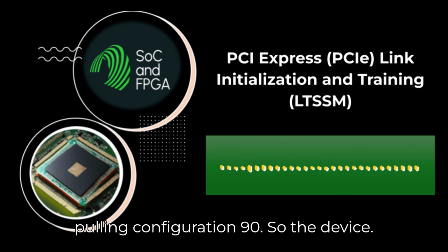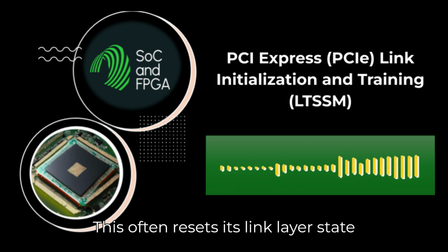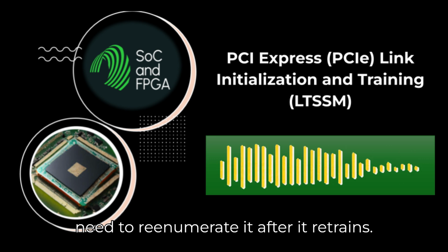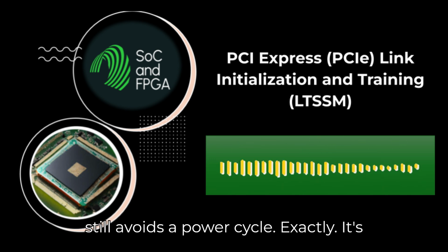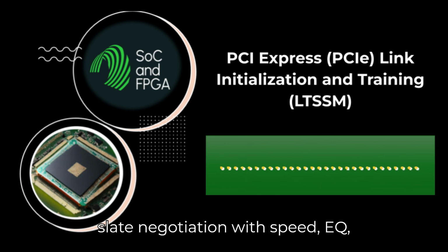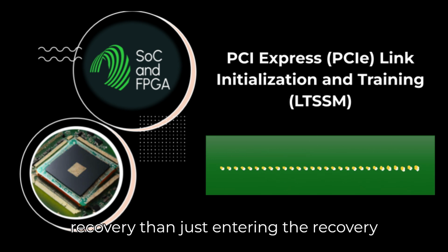Detect, then polling, configuration, and so on. For the device, this often resets its link layer state too, potentially losing its configured bus and device numbers, so software might need to re-enumerate it after it retrains. So it's a pretty forceful reset, but still avoids a power cycle. Exactly. It's a powerful recovery tool. Forces a clean slate negotiation with speed, EQ, everything. Yeah. Higher chance of recovery than just entering the recovery state.